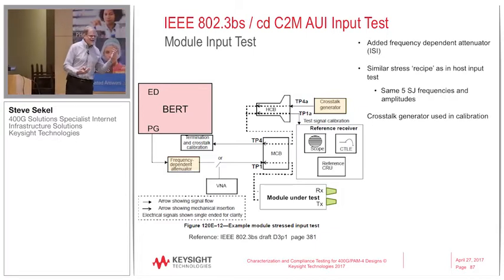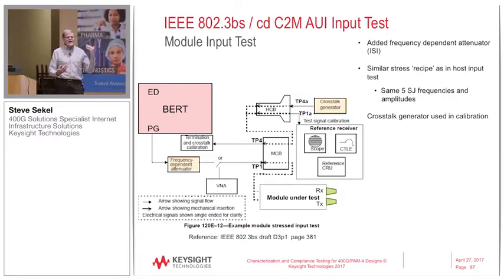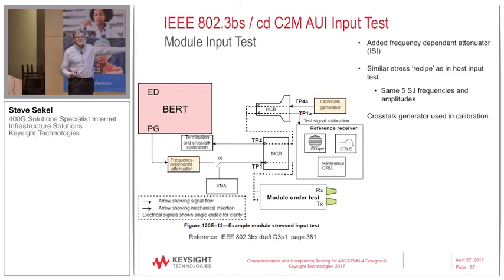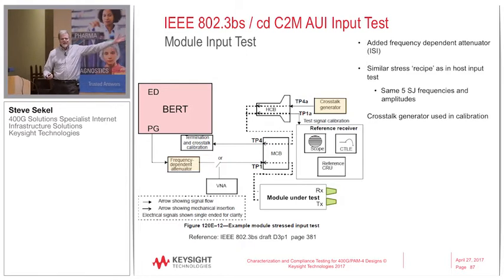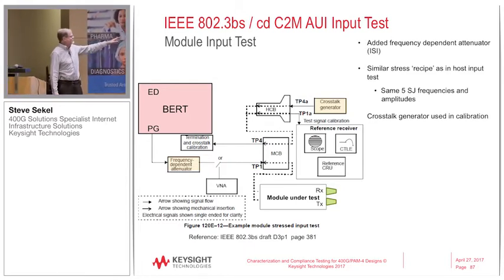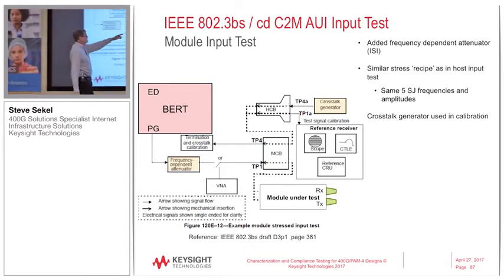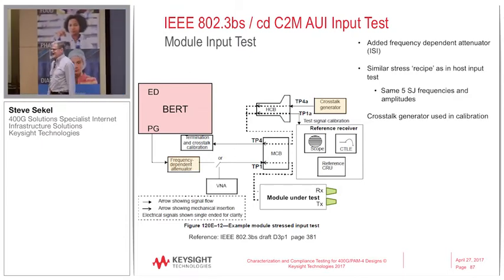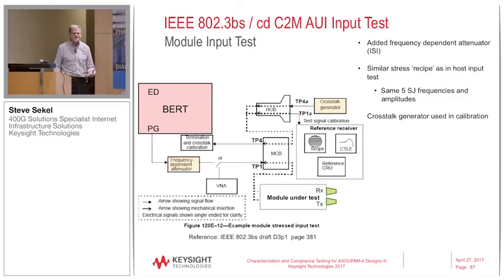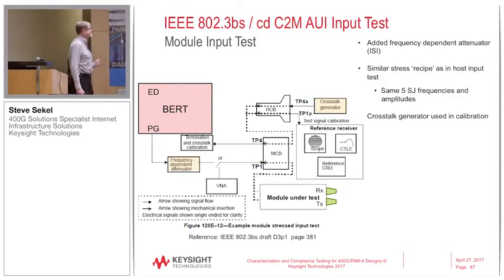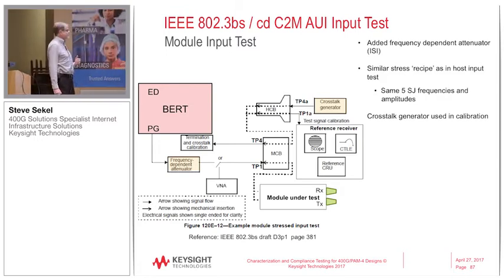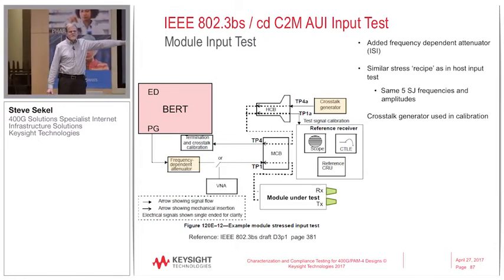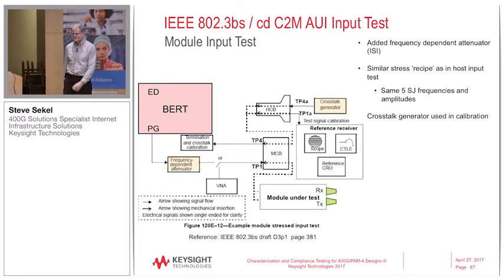You could make the case that for calibration purposes, I should measure the rise time of my DUT, since my DUT is going to be providing the crosstalk signal, if I'm really trying to make the most accurate eye and find out how much coupling I have. That's probably valid, but the standard tells you to still go with the worst case. Make it the fastest that it can be. And you won't be able to measure that without that CTLE and your reference receiver.